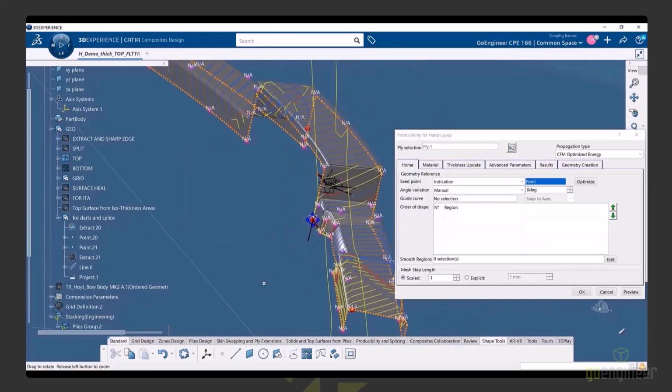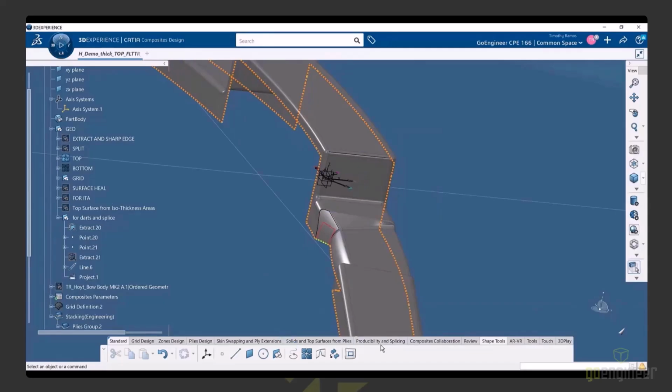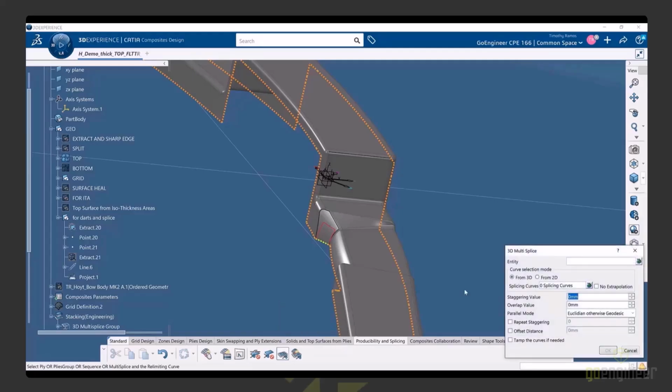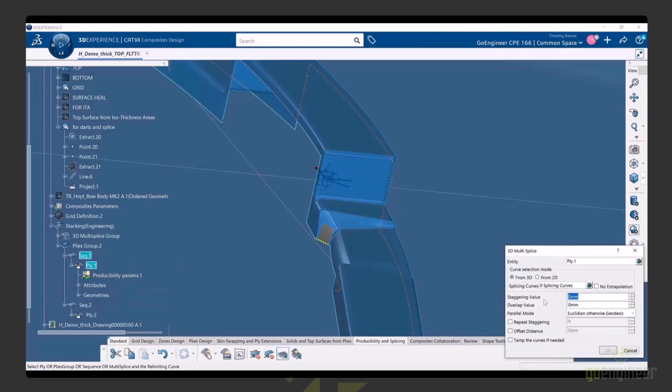In the scenario where the flat pattern exceeds the roll width of the material, we can choose options for splicing the numerous passes of the material roll, which accommodates the flat pattern. We can choose areas which will accommodate butt splices, no splices, as well as overlapping splices. Using the wireframe that I projected onto my surface, I define where the splice will be applied on my part.